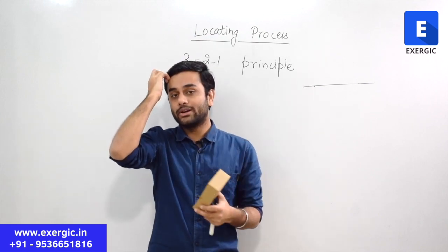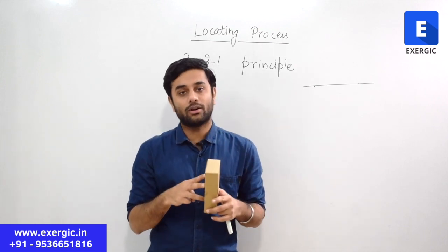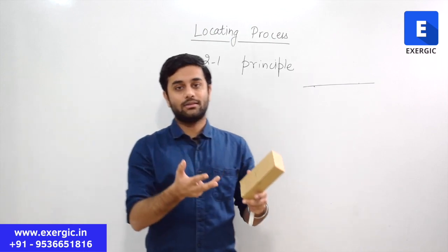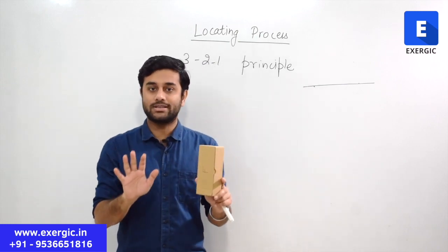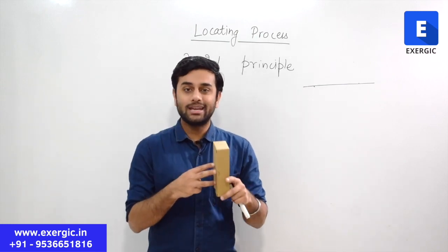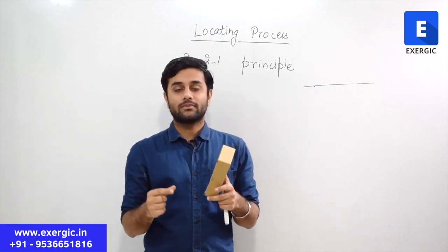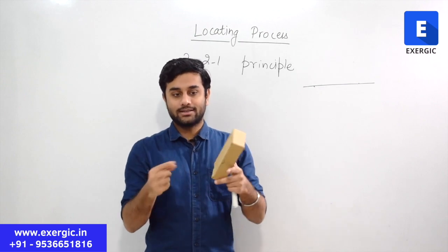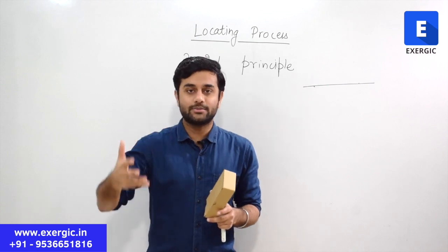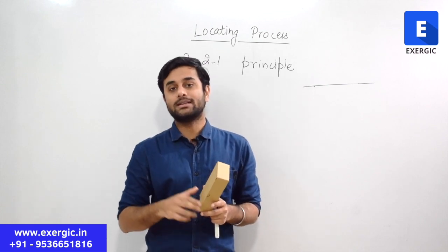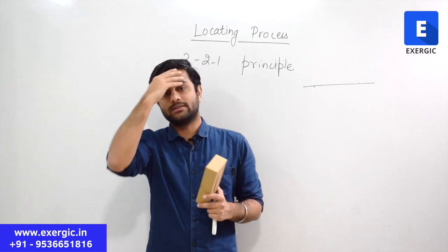But why not 4? Why not 5? Look, firstly, if we have defined the plane already, there is no need to provide extra points just to locate the point or plane. Logical enough: if you can do something with 3 points, why add more points? Why add more supports? The more supports you add, the more pins you add, right? Support is given by pins, as I showed you. So every extra pin needs extra arrangement. Obviously, it occupies space and has some cost. So we will not try to use unnecessarily extra pins.